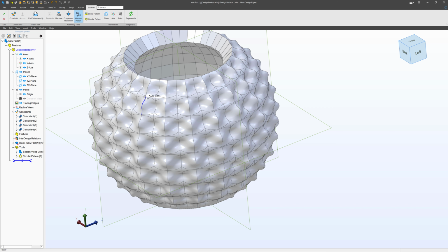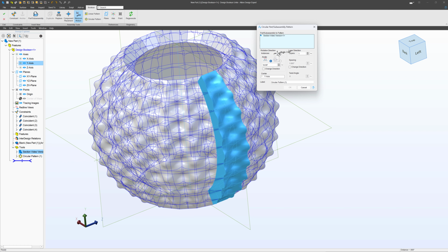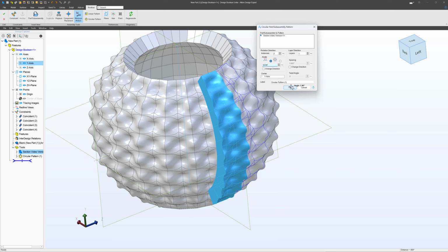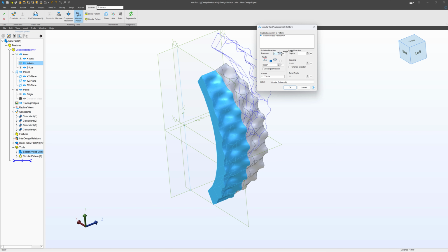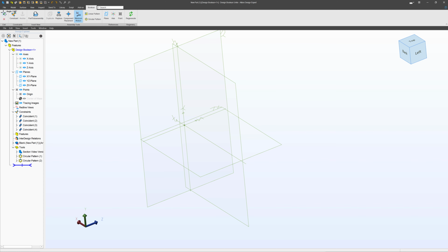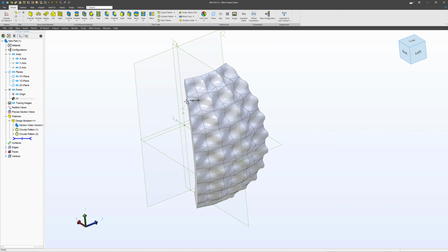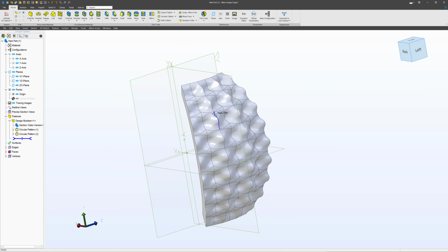But I want to address this in another way. So I'm just going to go back to Edit, make sure that I'm working with 2 instances. And we'll say OK to that. I'll make another circular pattern with the same y-axis specified. We're going to say 18 degrees in the other direction. And so we make 1 on each side, and we'll go ahead and accept that Boolean unite.